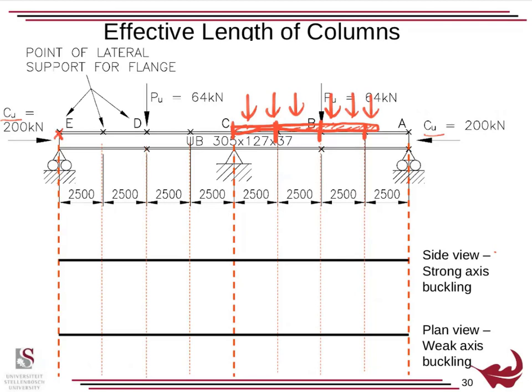So as we load, the floor carried by the beam will go up and down. However, if the beam tries to buckle laterally, this floor will stop it from moving sideways. So there is a lateral support where the floor is fixed to the beam. And if this, for instance, was continuously welded, you'd basically have a continuous connection between the floor and the beam. So a lateral support is something that moves with the beam, but it prevents sideways movement. A support like here prevents both sideways movement and up and down movement, but a lateral support only prevents movement sideways.